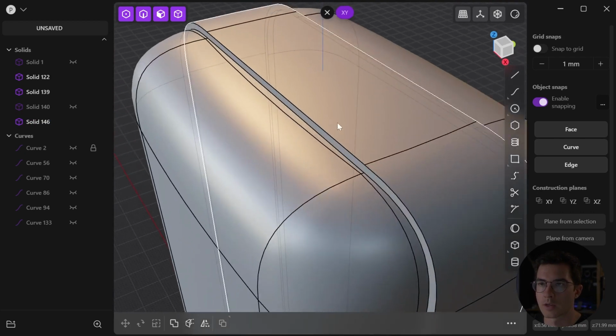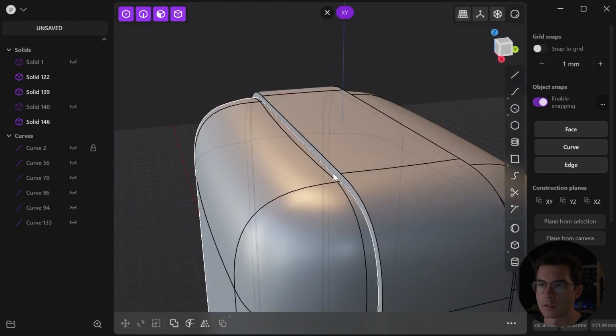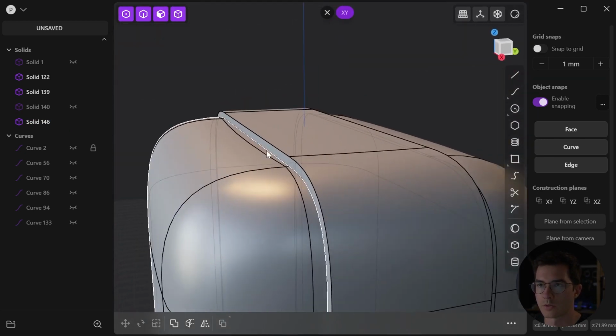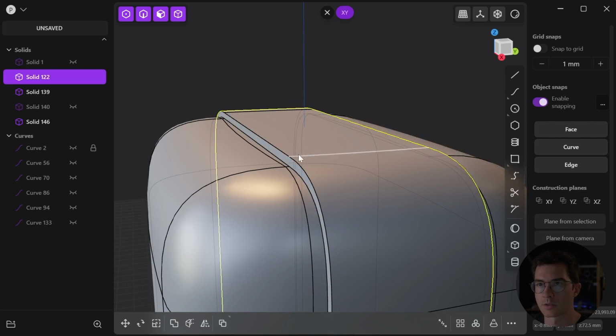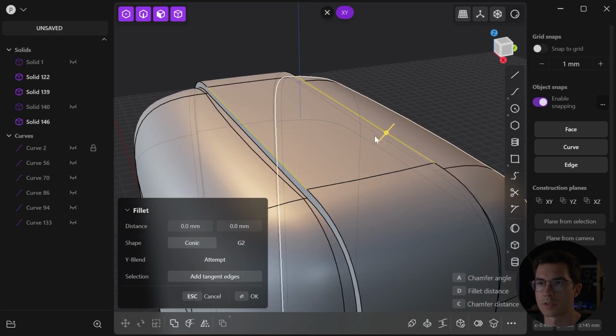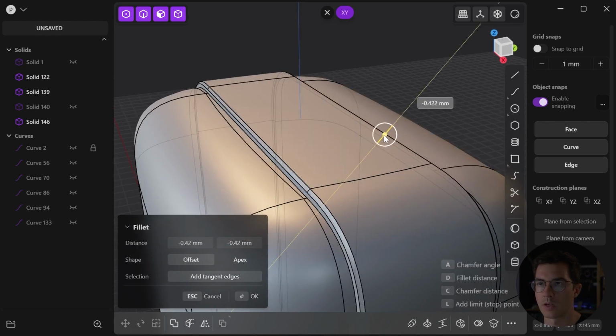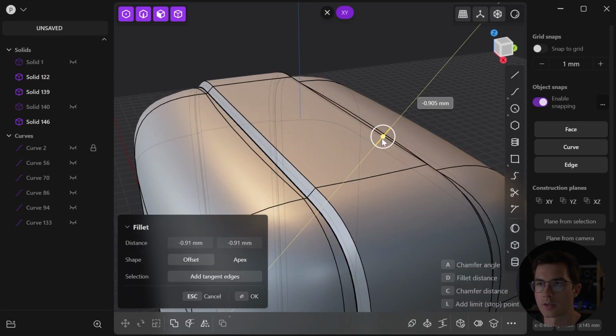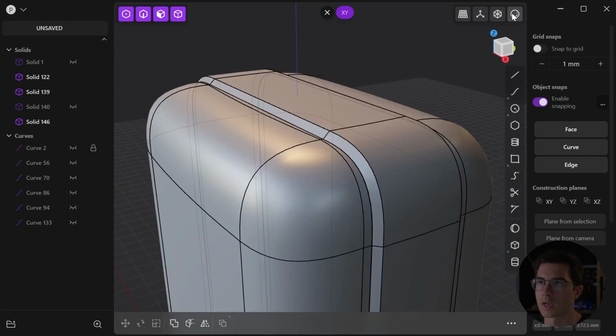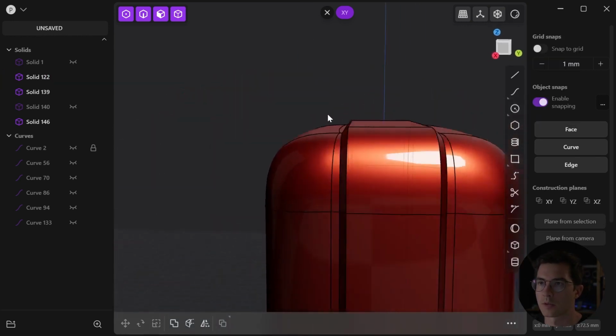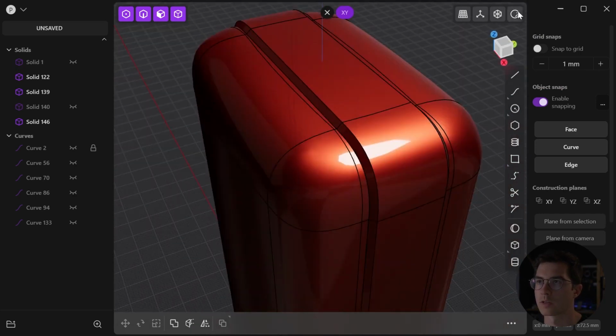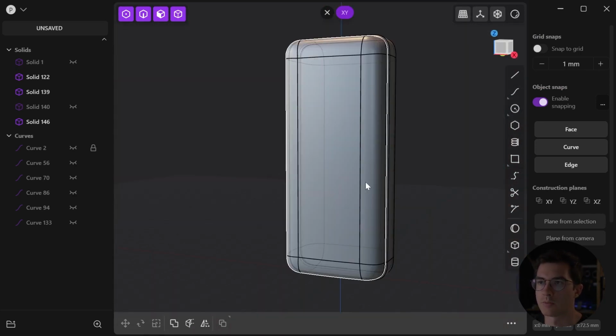All right, let's quickly make the chamfer here. We want to soften this hard edge. So we go into this center piece and then highlight both of these edges. And if we go inwards, we're gonna create a chamfer. You can see we're gonna go about 1 millimeter. So hit D for the distance and then type in -1, hit OK. So again, we can check our progress with the different shading tools. It looks really nice. Okay, let's continue with our split.